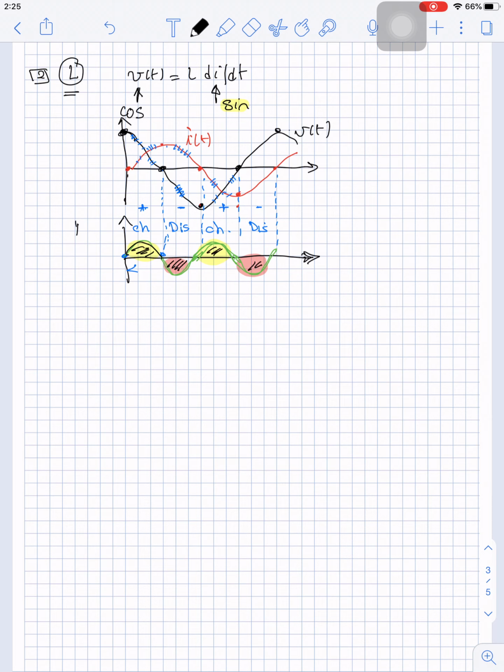So this is P of t, and this is time. How many charge-discharge cycles did you do here per cycle? The source did just one cycle, but your power did 2 cycles. So you did a charge, discharge, a charge, discharge. This means that the frequency of the power change is double the frequency of the source change. And we will do the proof for this mathematically.